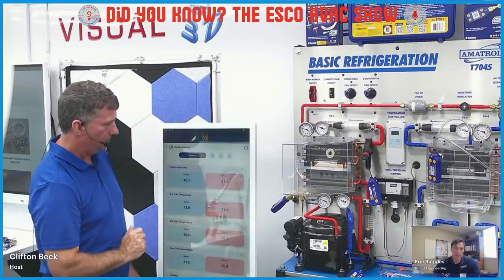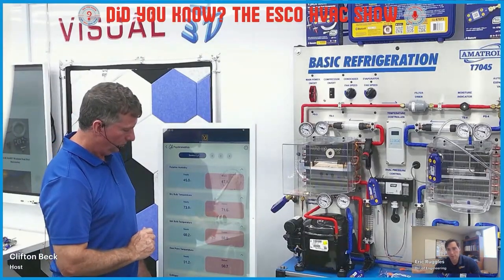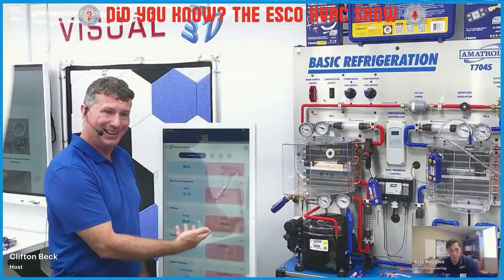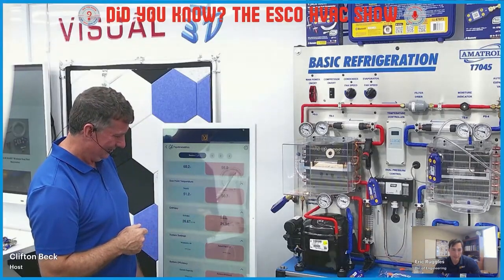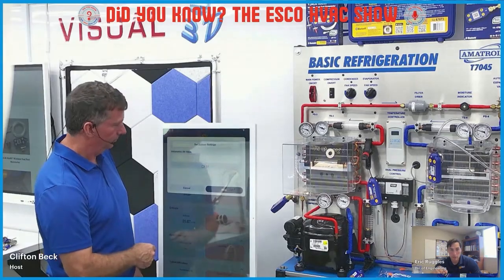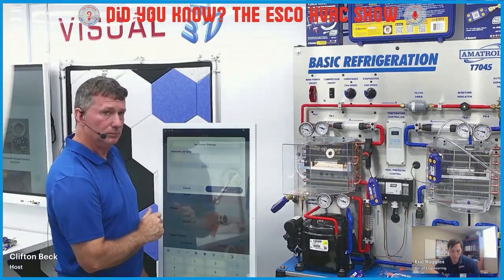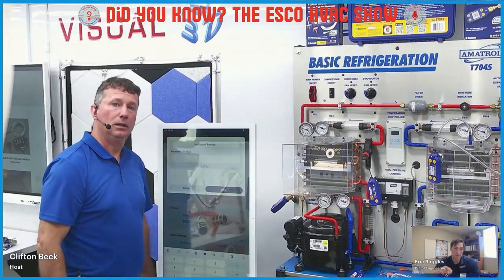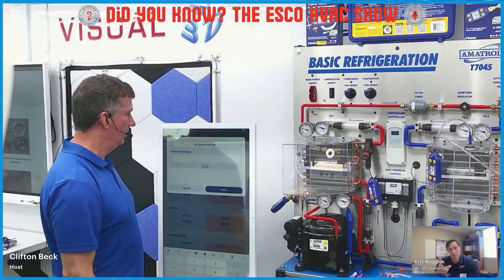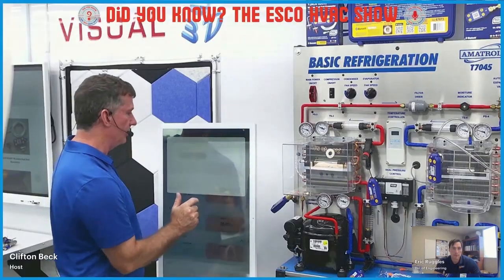Okay. And again, this is going to show you the relative humidity, dry bulb, wet bulb, and dew point. That's what's coming from the sensors. If you scroll down, it'll show you the enthalpy difference. Look at that. Okay. We're using that to calculate capacity. So if you click on that blue box, you can either input the volume of air that the fan's supposed to be doing, or if you use your anemometer, it'll show the last 3 anemometer readings. No kidding. Actual, true calculated airflow then. All right. Nice. We'll just pick a random number on this one.